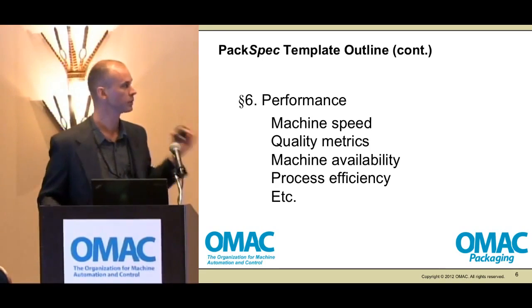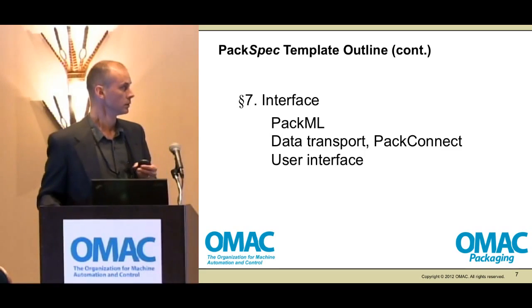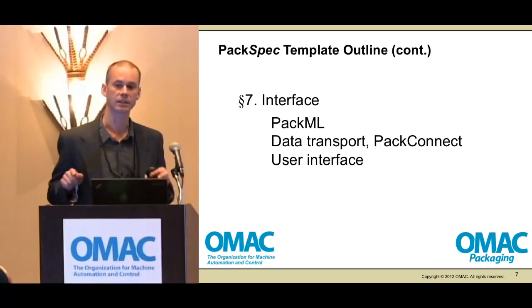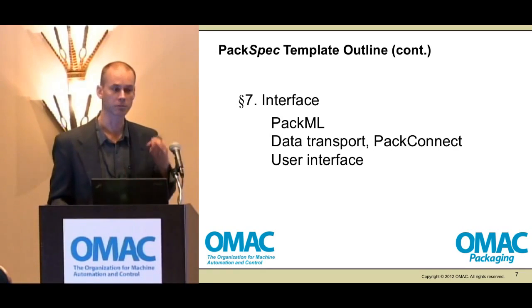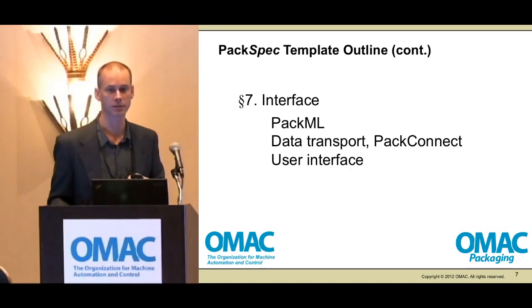The interface part, this really is the PackML part. So here the end user really needs to define exactly which pack tags are supported or need to be supported. In a given mode, exactly which machine states need to be supported, and so on.